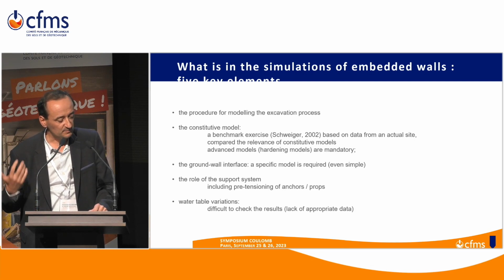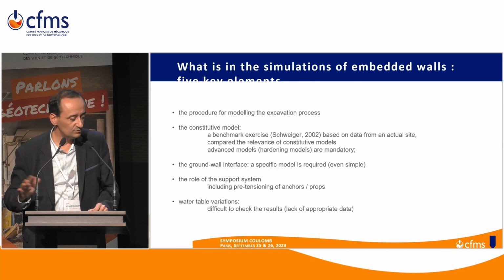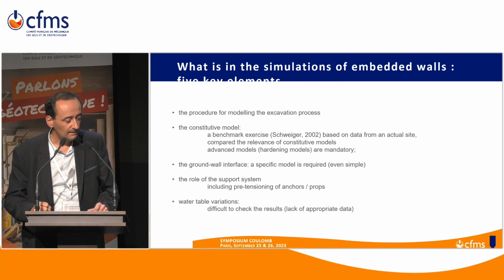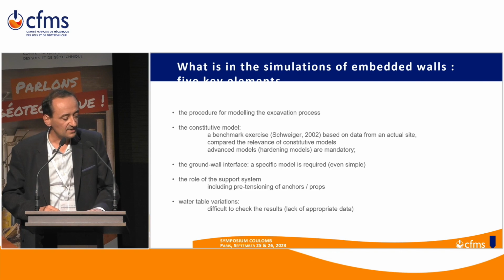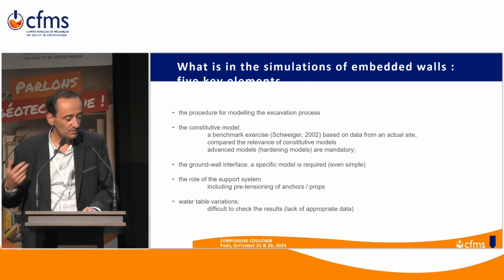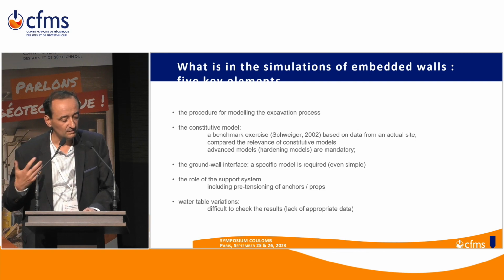You also have to pay special attention to the constitutive model, and we know since the work by Schweiger 20 years ago, they organized a prediction exercise on an actual site in Berlin, and they compared the relevance of constitutive models by making comparison between predictions and measurements on the real wall. And well, we can make all sorts of comments on the comparison, but one of the very clear conclusions is that you need at least a hardening model to have a reasonable representation of the wall behavior.